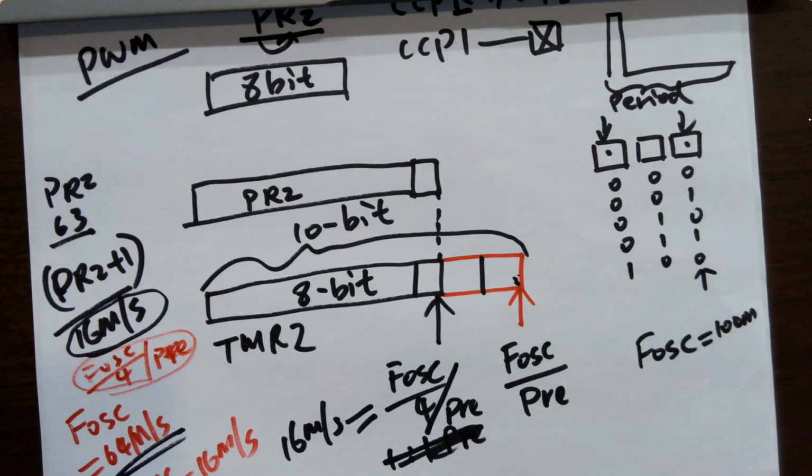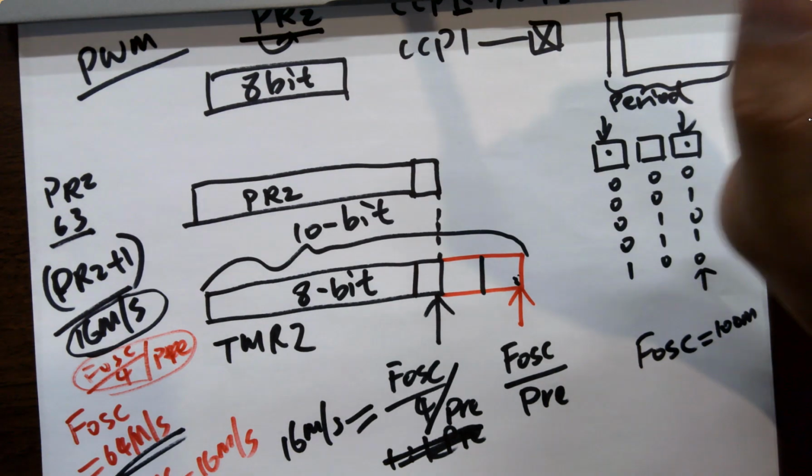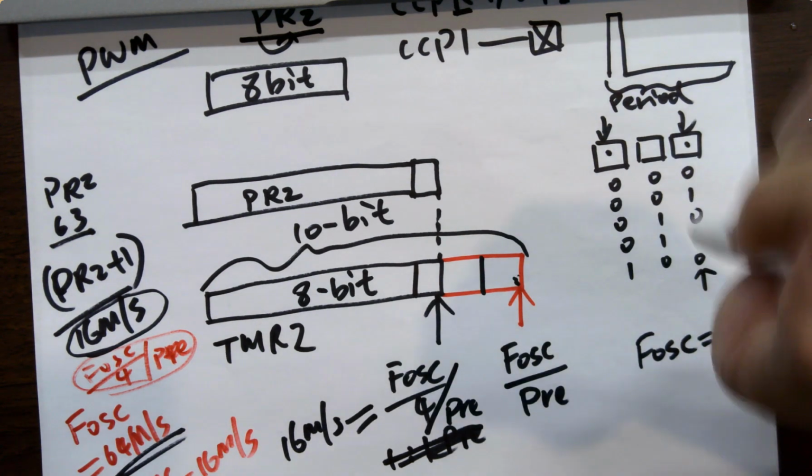You get a time. Does the prescaler have to be a power of 2, since it's done with that kind of hardware? No, they designed it that way. It's customizable. You can do a 1-to-2 prescaler if you want. It's not a big change. That's probably why the designer didn't do it in Microchip. They have 1-to-1, 1-to-4, 1-to-16, but definitely you can have like 1-to-2, 1-to-8. I think Arduinos have 1-to-8 sometimes, if I'm right.